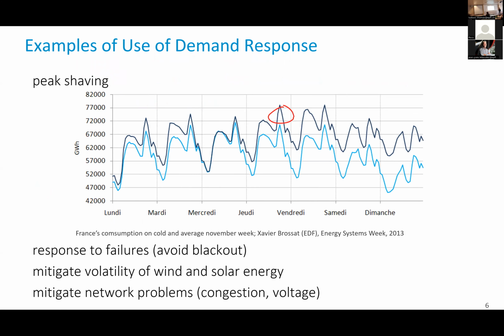The primary use of demand response today is for doing what is called peak shaving. Peak shaving means cutting the peak. Here is an example of the France consumption in November on different years, on an average year and on a cold year. And we see that the demand peaks, but the duration of the peak is very small.